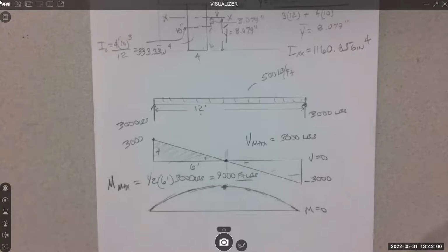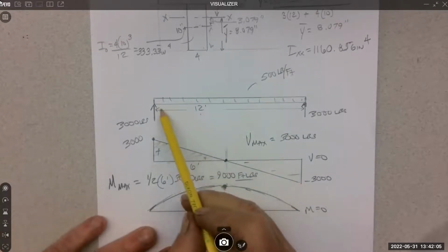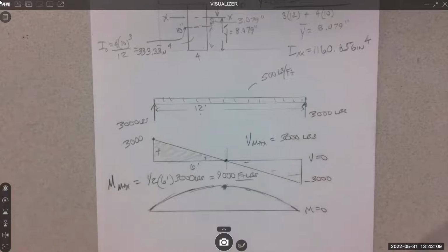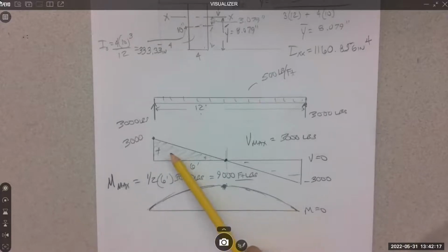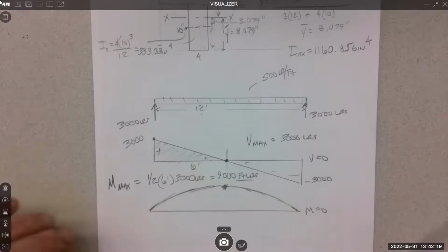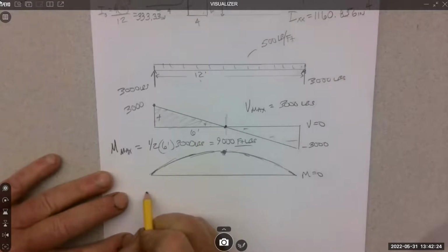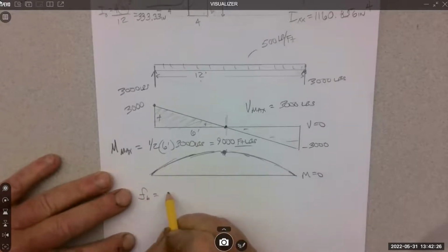Okay, that's good. It's positive. That's just because that deflection curve kind of is concave. Smiley face in the deflection curve means it's positive. This also means it's positive because it headed up. So then we would work our way towards bending stress, which is MC over I.